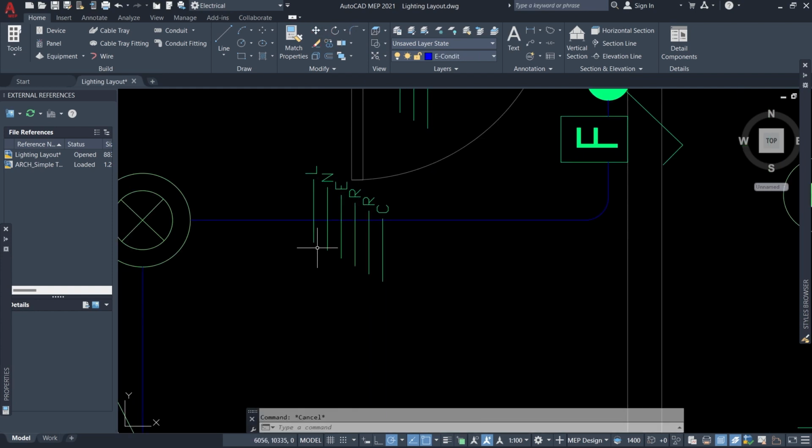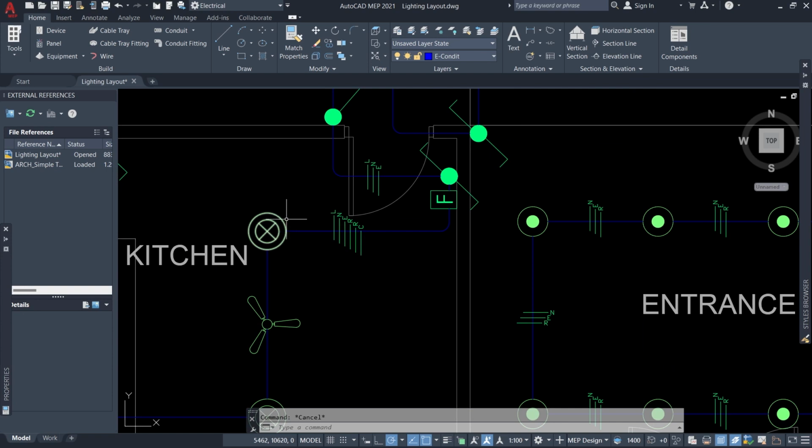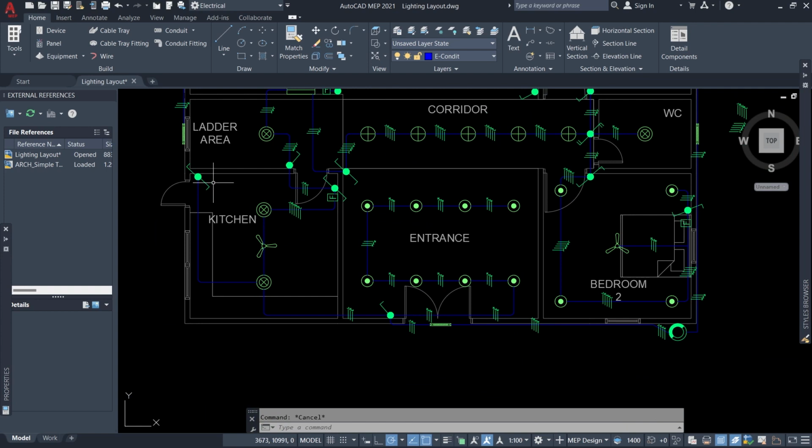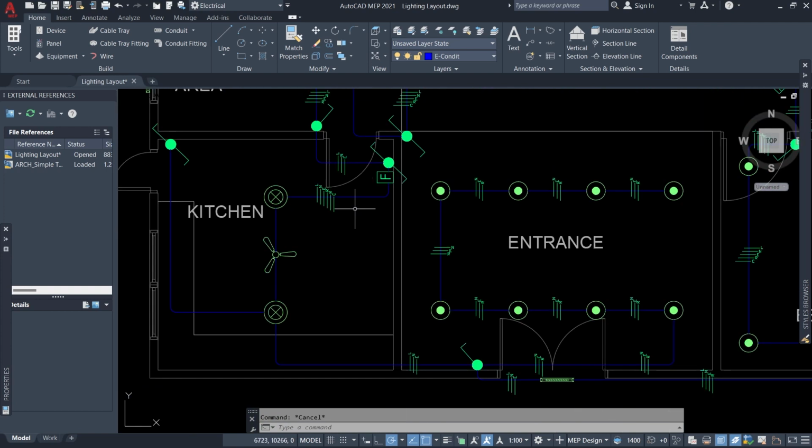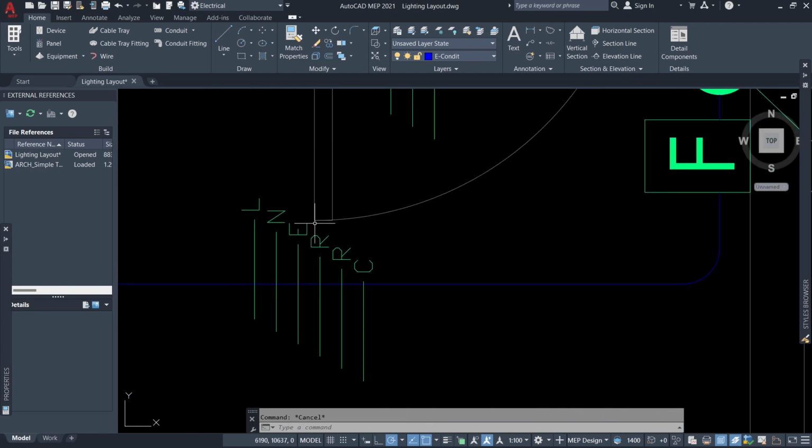We have 2 returns because there's one for this light, one for the fan, and then the control is going straight into the other switch. Okay, very fair to understand.